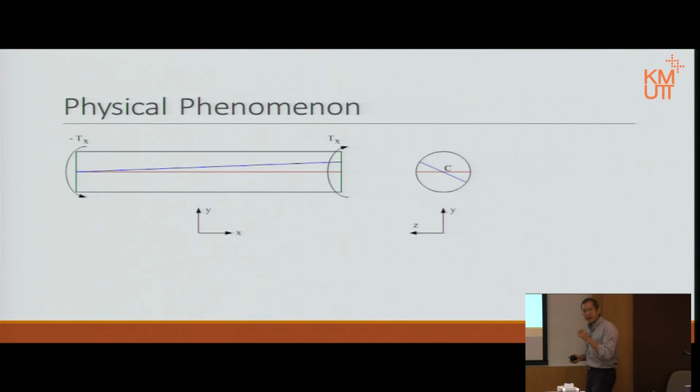Now, just to be precise, that is the angle we call gamma. That is the angle we define as the shear strain. I emphasize, this gamma is the shear strain. The angle you see on the cross section is in fact another one. We use the symbol phi. This one is called the angle of twist, meaning how many degrees or how many radians, depending on the unit, it has been twisted.